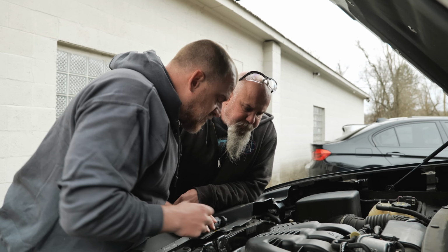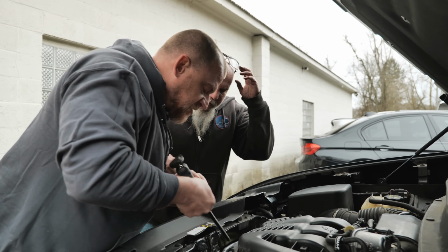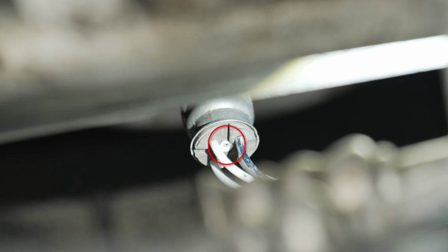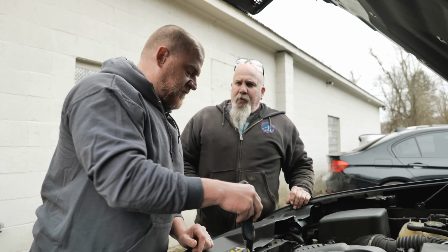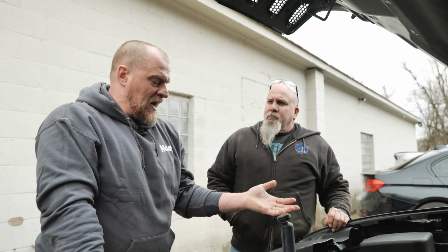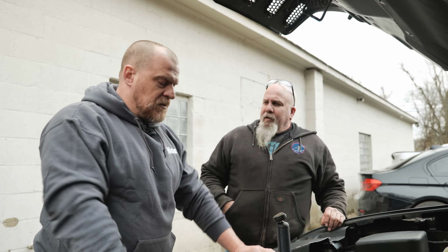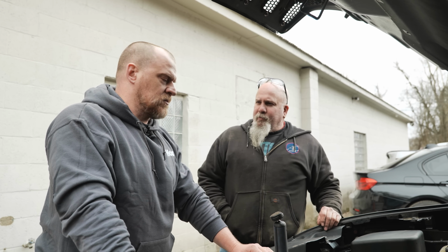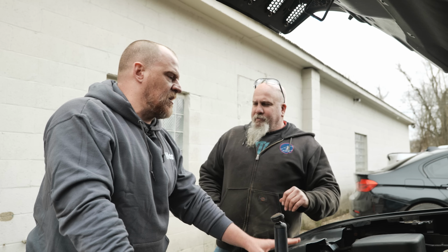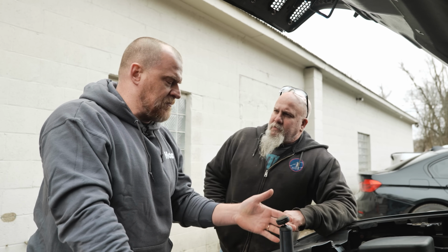And you have an air port. You can see that. Caleb, come over here so you get a shot of this. There's an air port. You see the little white part in the middle of that sensor? That's your air inlet for that oxygen sensor. So it might be okay. They might have driven it enough now that you can just clear it and drive it. They might not have to do anything, but if it happens again, the O2 sensor will need to be changed. Probably. If it happens again, make sure he's open to that possibility.